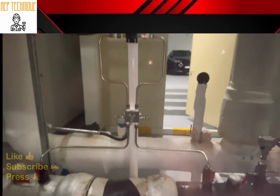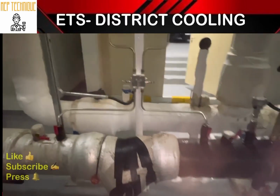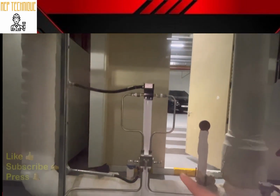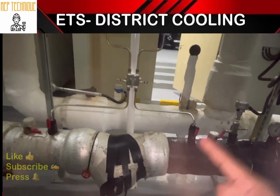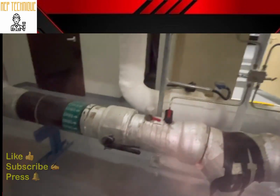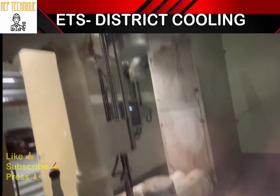Then this is the DPT for monitoring the strainer. This is the strainer in the chilled water supply line, and you can see there is one on the primary side and one on the secondary side. Both are connected in the chilled water line, and this is the DPT, differential pressure transmitter. If your strainer or chilled water line is blocked, the DPT will transmit the data to the PLC for this information. After that, again there is a butterfly valve to isolate and regulate the chilled water line. These are the equipment you will find in the chilled water supply of the primary circuit.